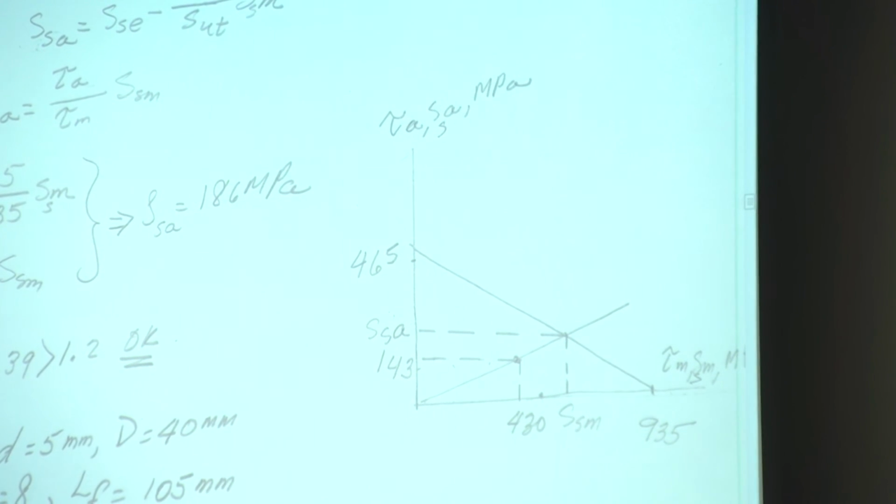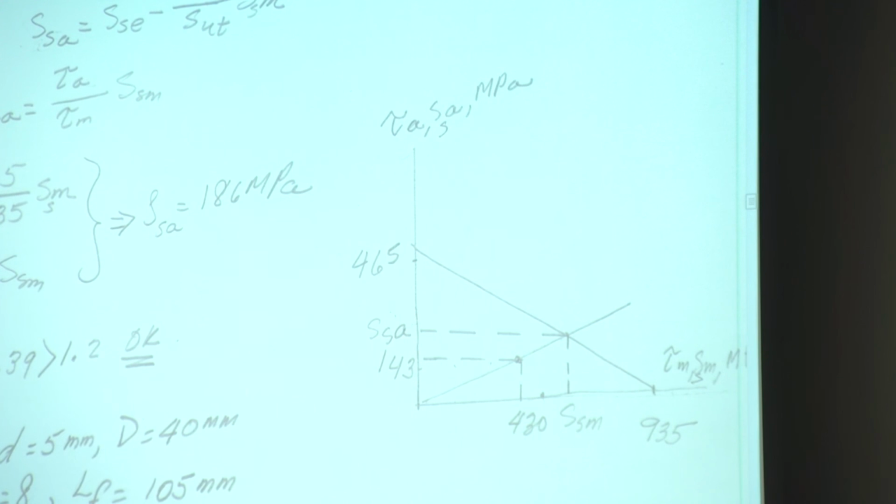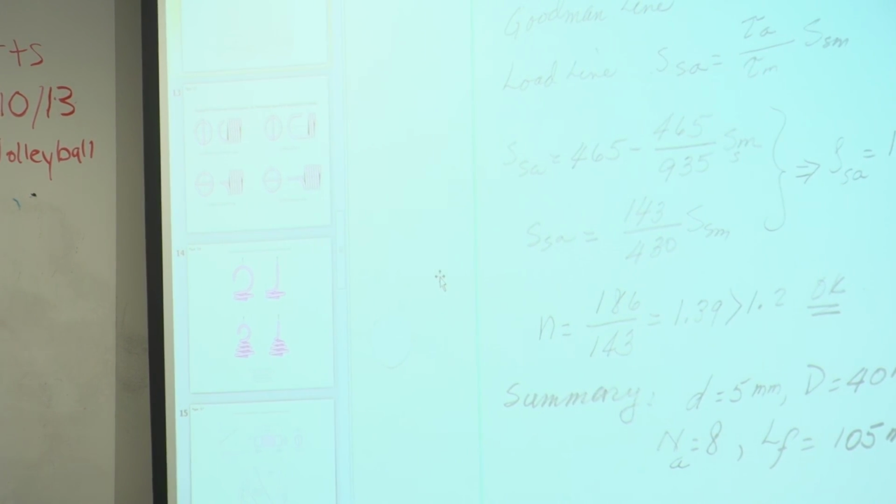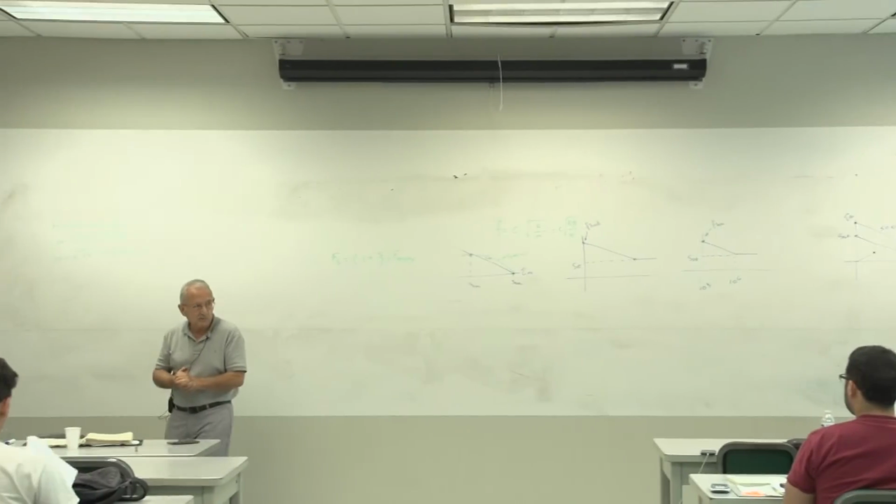In shafts, the deflections got unduly high. Here, that was bending deflection. Here it is compressive deflection. The deformations will get unduly high, which means that you will either reach the solid height or you break the spring. One of the two. And neither of which, of course, is desirable.